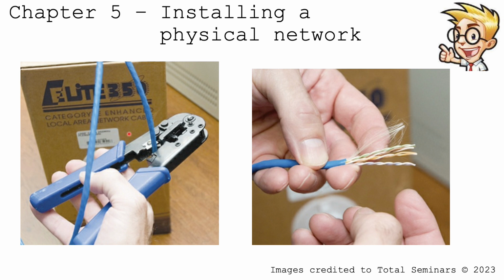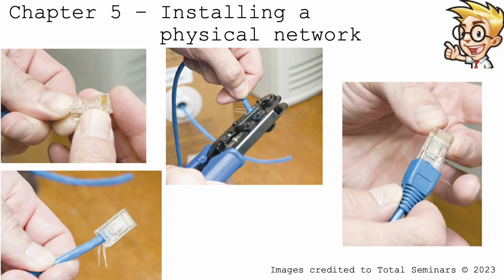Okay, so here's a cable crimper and stripper. The bottom strips the cable. So this is a stripped cable with plenty of room in case there's a mistake. Then you can cut it again and make sure, but always have a little bit of room for air.